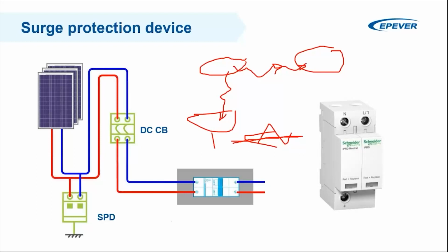So it's better, depending on the type of the installation, to have a sort of surge protection device which guides the high current to the ground. Normally, let's say this device is open circuit, but when the voltage or current exceeds a certain amount, then that's short circuited and it guides, let's say, the current to the ground instead of to your system, and this protects your system.